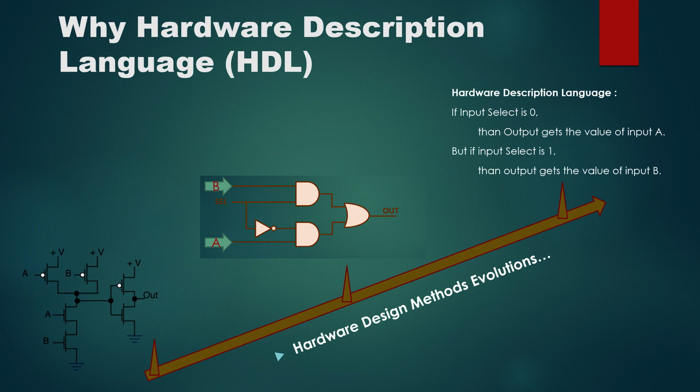So when we grew to little more complex systems and ASICs were getting more dense and complicated, we started using logical level design, and we jumped from transistor level designs to logical level designs. Just a quick note for those who are not familiar: logical level design is the schematic level design where we use basic logic gates like AND gate, OR gate, NOT gate, etc. to design our digital system. But the problem was that with time, the density of logic gates and transistors grew very fast, and ASICs grew too. So design modifications and corrections sometimes got unmanageable.